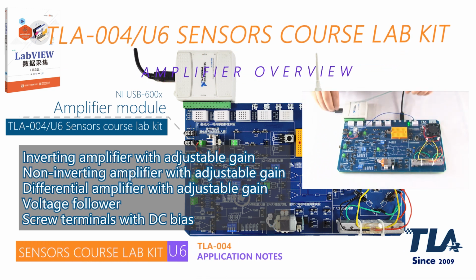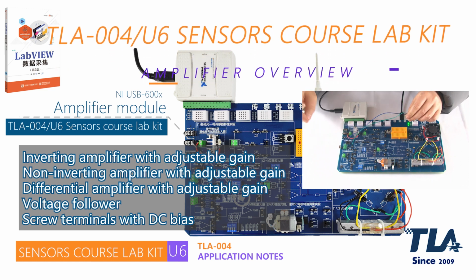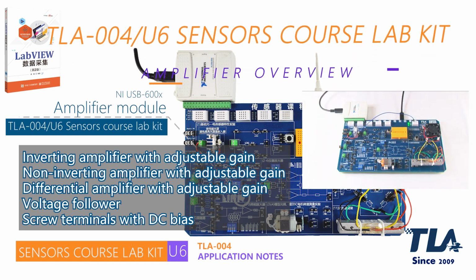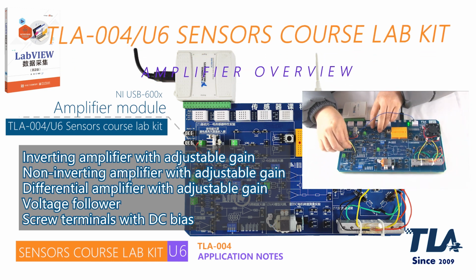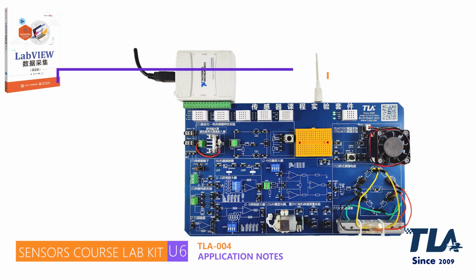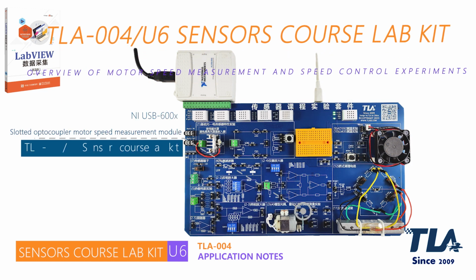The combination of the human pyroelectric infrared sensor and the inverting amplifier can form a signal conditioning circuit that meets the characteristics of the human pyroelectric infrared sensor. During the experiment, the experimental software DAQware for NI-DAQ-MX is combined to help students master the working principle and characteristics of the pyroelectric infrared sensor for the human body. Combined with LabVIEW programming, we can participate in the whole process of the sensor experiment.